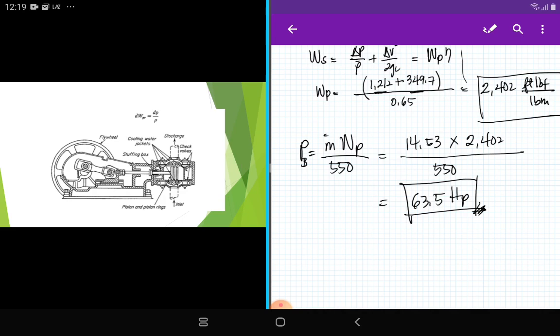So for compression, assuming that we are considering only the pipe in and out of a compressor, we have to consider that there's no change in the friction losses, so we cancel out the friction losses head. There's no potential head because there's no elevation, and assuming that the velocity doesn't affect, only the pressure head will be equated to the shaft work, which is that of the compressor.